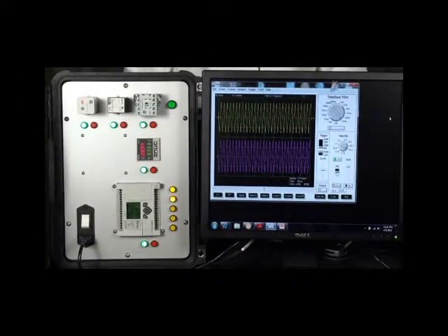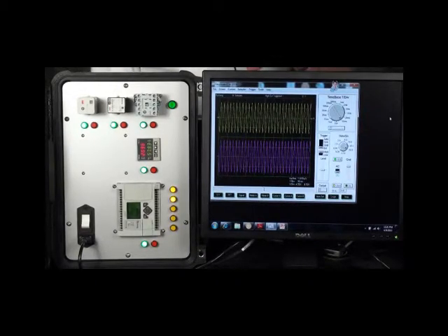As I generate these voltage sags, I want you to take a look at the monitor that displays the waveform, and we'll see the effect of that sag. And then on the right, the control cabinet itself, any contacts or counters or anything that drops off is actually going to turn on a red light. So we'll trap the fact that it's dropped out and come back on momentarily.